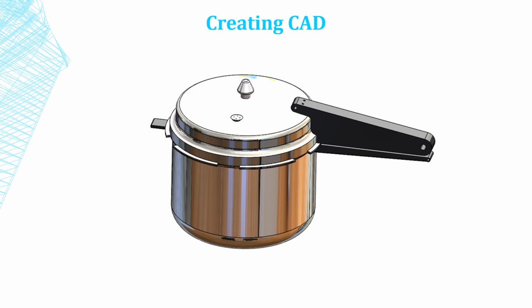If we have thick geometry or parts which can't be created as 1D line bodies or 2D surface bodies, then we can create 3D bodies. Examples are engine blocks, pressure cooker. As an example for FEA steps, we will explain the example of a pressure cooker for further steps.